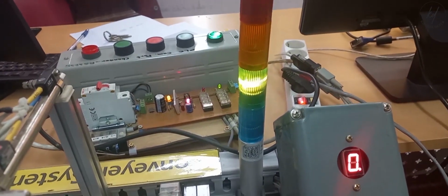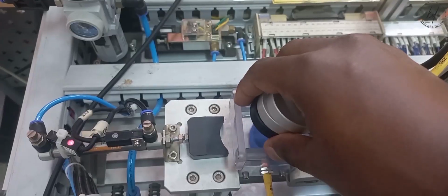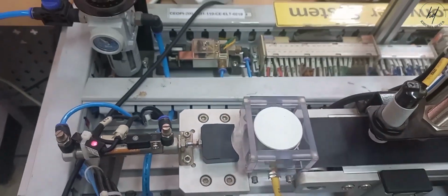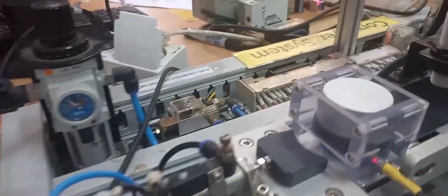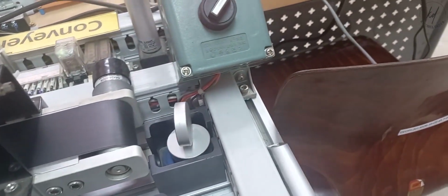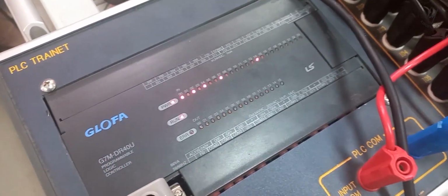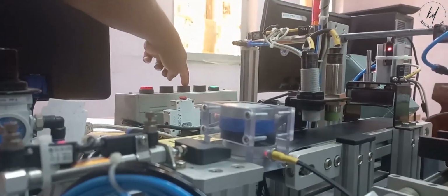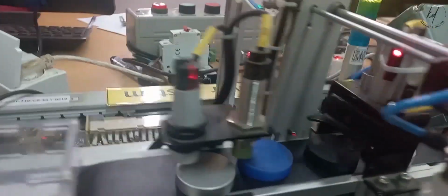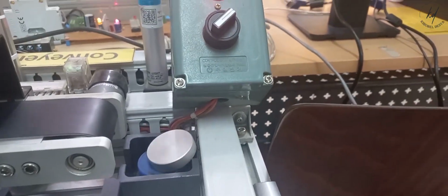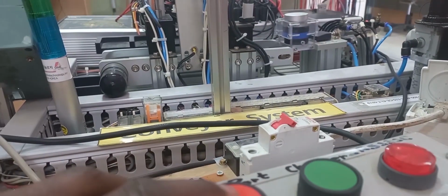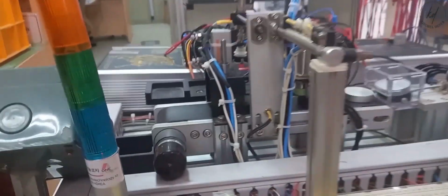As we know, the program executes line by line. When any object enters the box before 10 seconds is completed, and we bring an object in front of the magazine sensor in row 8, the re_run coil tag is energized, and its immediate effect in row 2 de-energizes MX1, and as a result both MX2 and MX3 become similarly de-energized. After MX3 is de-energized it goes to row 2 and now the re_run normally closed contact is returned to its state. As a result, the MX1 coil tag gets supply and activates the solenoid valve, and these processes take place repeatedly.